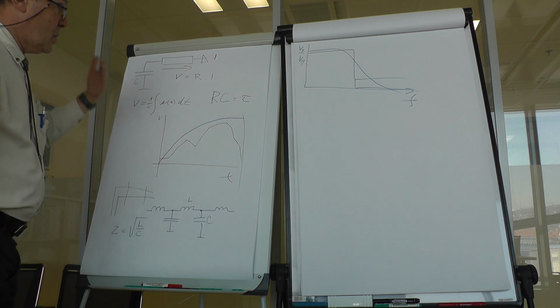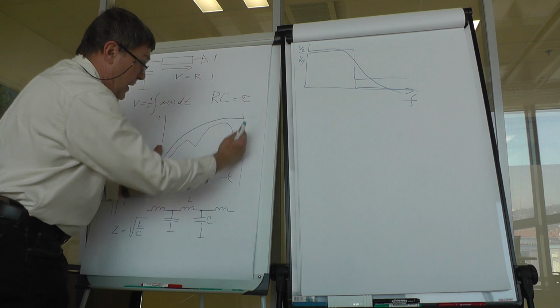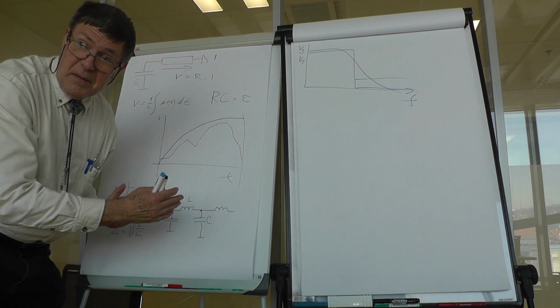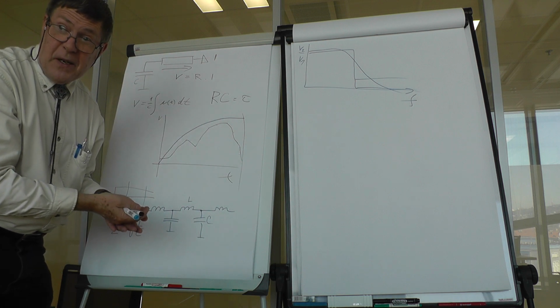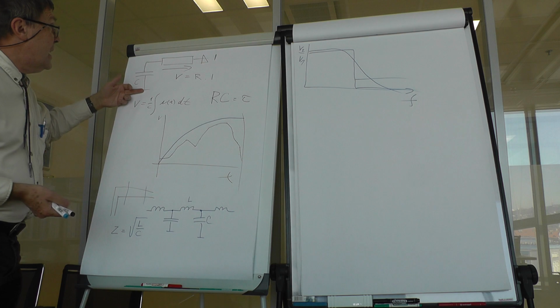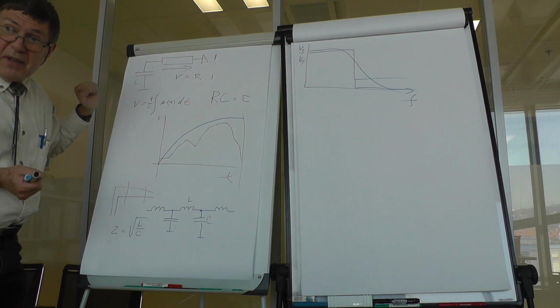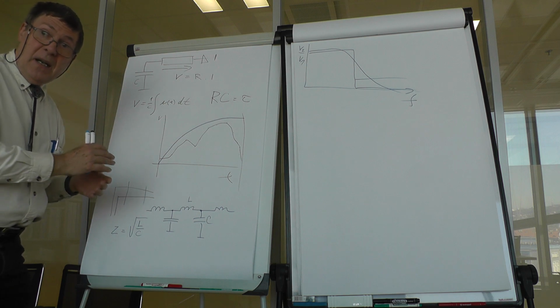So that's something you would fully charge the capacitor, and then you would take the circuit, sample in time the voltage, and convert it using Fourier transform, and you would get easily the frequency response of this circuit. That's quite easy.